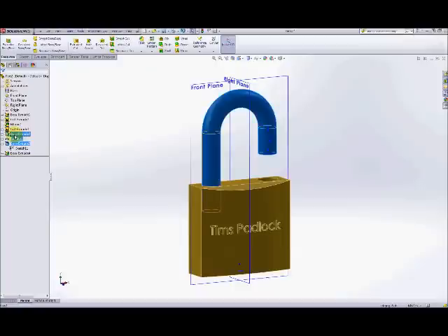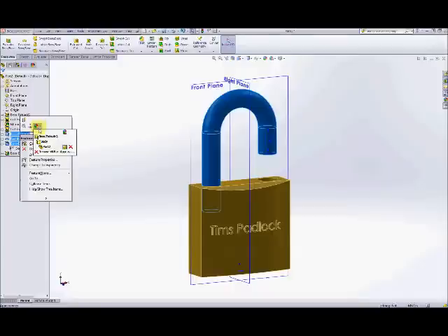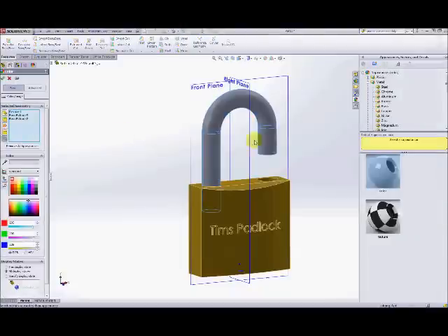features that create the shackle, and if you right click on that and go to appearance, you can then select these. You can select a variety of options. You can select the entire part, you can select the particular body, which in this case is the same thing, or we can select just that feature. So if we select the feature, on the right hand side we have a whole bunch of features that we can select, plastic, metal.